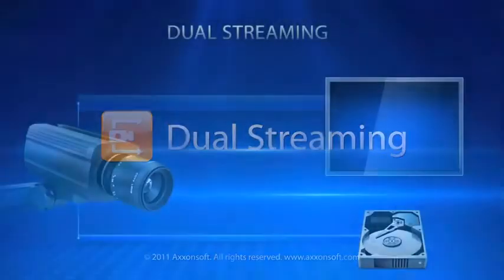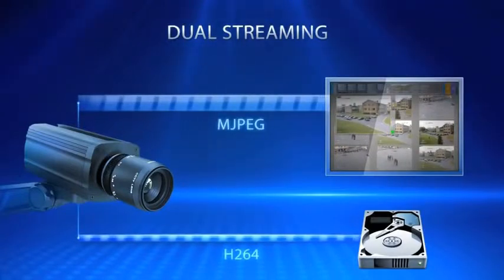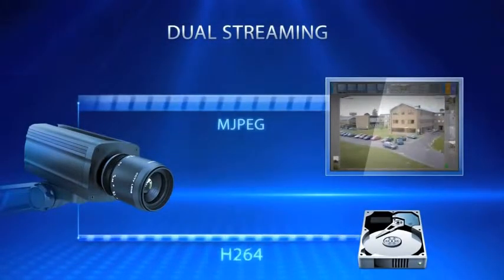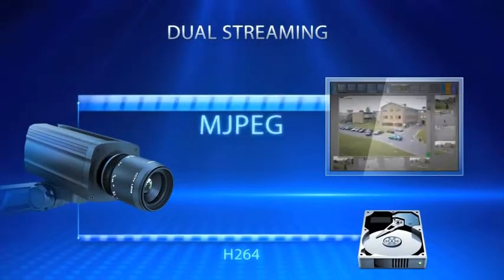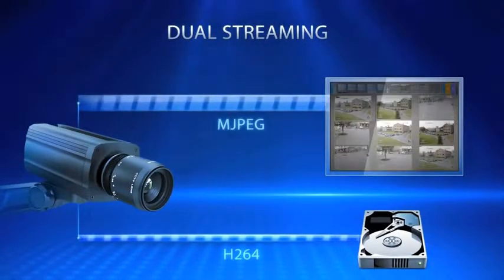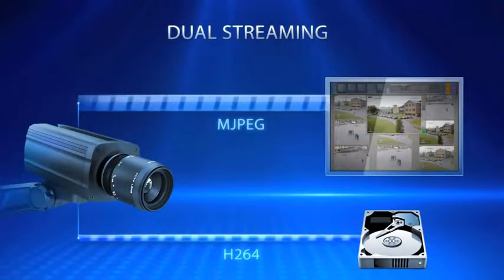Dual streaming. Suppose your camera can send two video streams in both the MJPEG and H.264 formats. Then it would be sensible to use the higher compression H.264 stream for archiving, while using the easily decompressed MJPEG stream for viewing at a workstation. With this dual stream support, you'll save disk space on the server and unload the CPU at the client workstation.